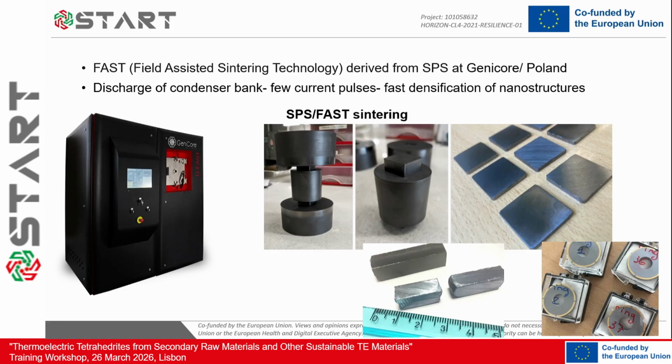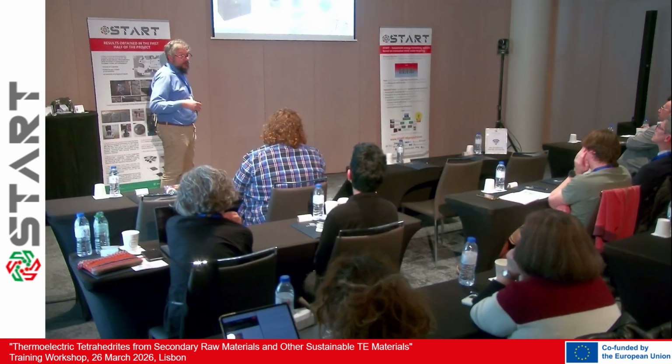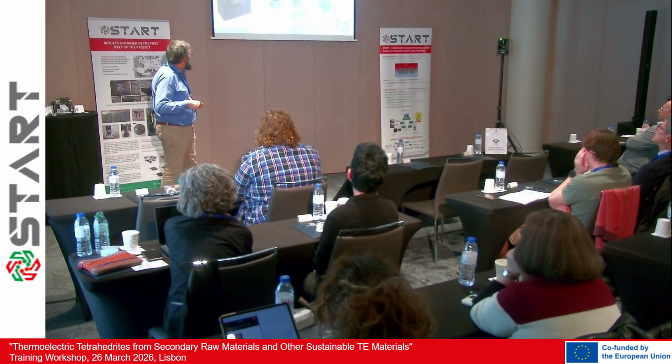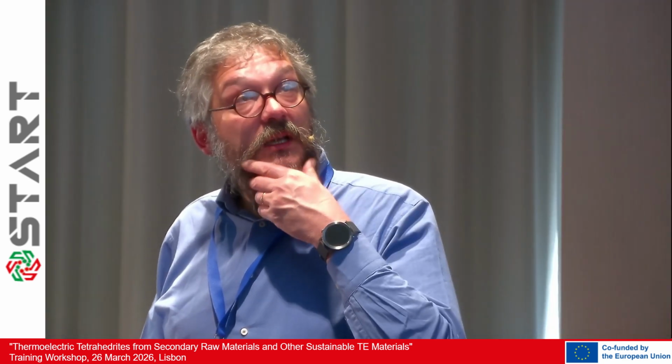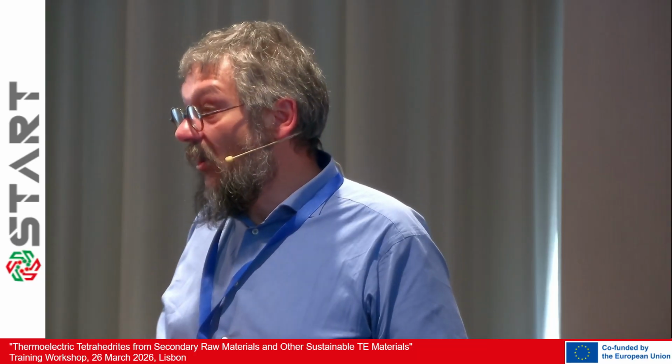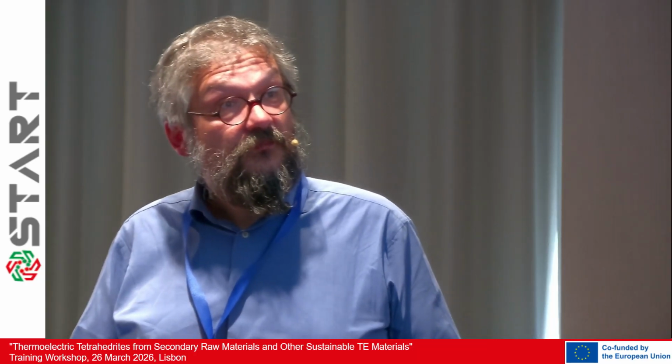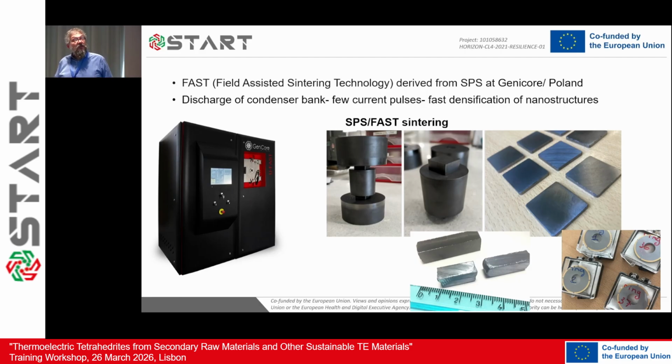So current is passing through it, going through the powder, and with the action also of the pressure on top of it, it's a way to reach in minutes almost full consolidation. And this gives us the possibility to get these pellets in different forms. This is one coming from our machines. I keep this because, as you can see, it's not neat as a shape.